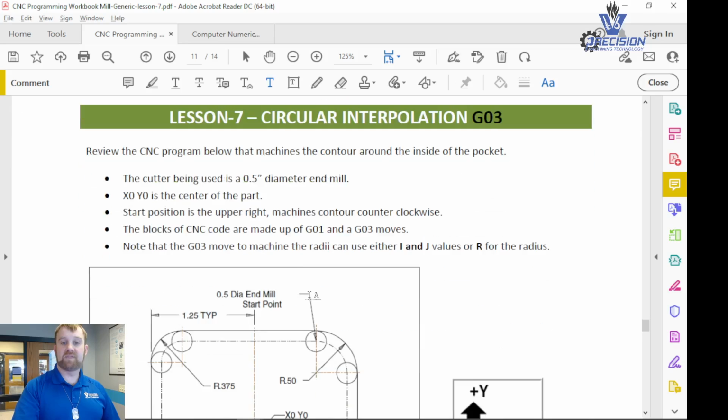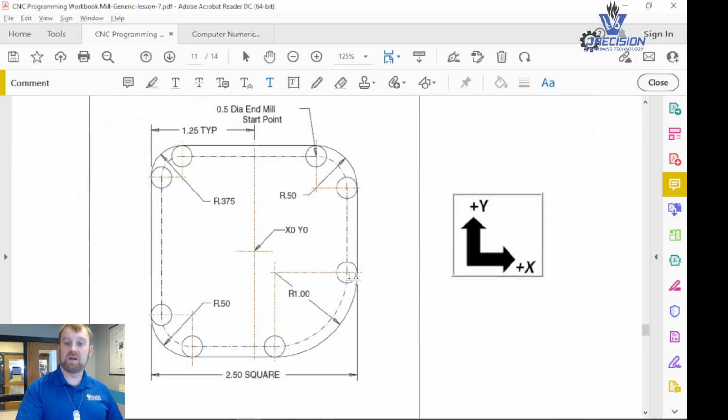And then do the same thing, but this time come down here and you're going to mill around the inside, and you can just plunge at any of those locations that you want to. You can plunge down and make a counterclockwise slot milling around the inside of this. Okay, it should have an 1/8 inch outside wall basically on the outsides here. Okay, so write an exercise